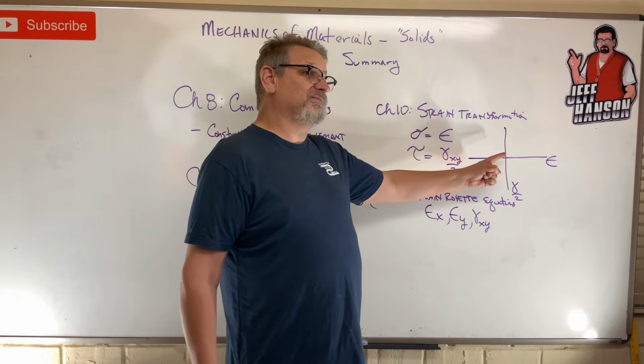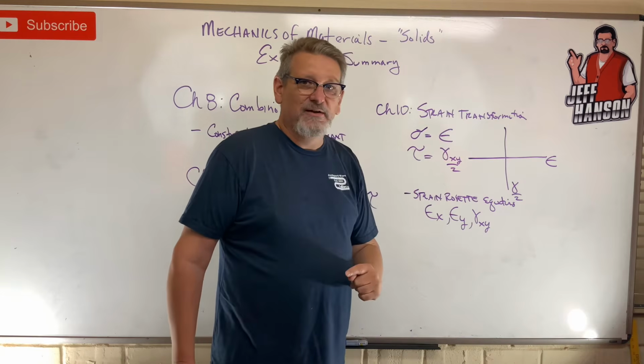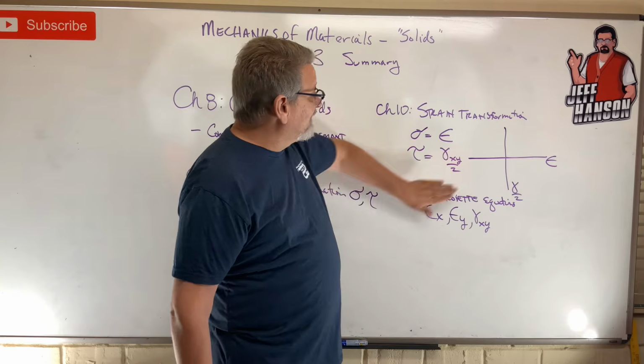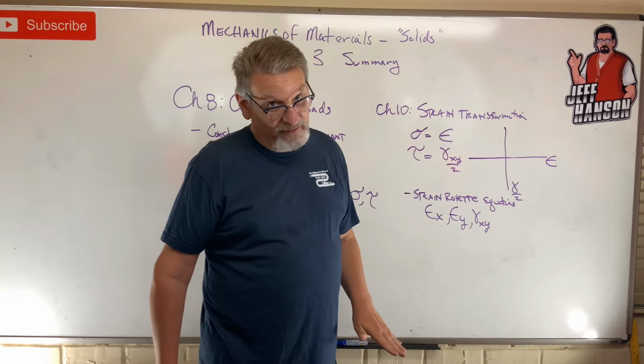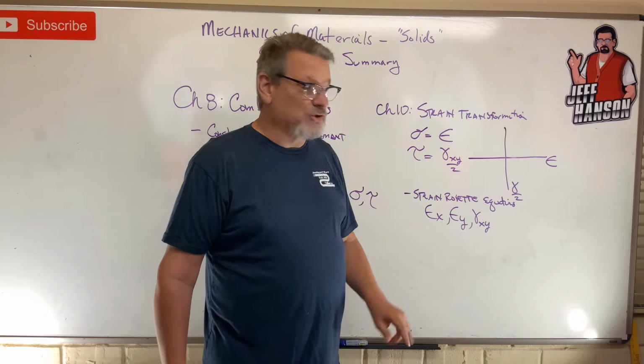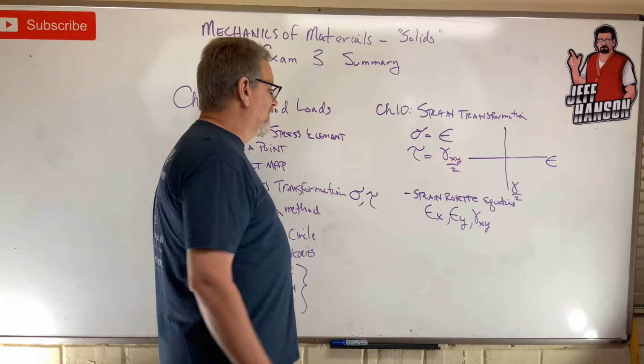tell me what the maximum strain is. What is the maximum shear strain? Okay, so I can take these values that I get from the strain rosette and then come back up here and have to apply them inside of a Mohr's circle, okay? Kind of a 2-for-1 special. We'll do one of those on a sample problem, so stay tuned, okay?